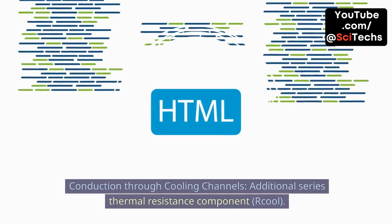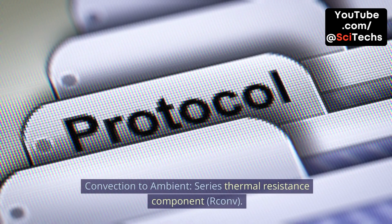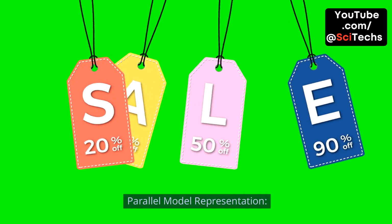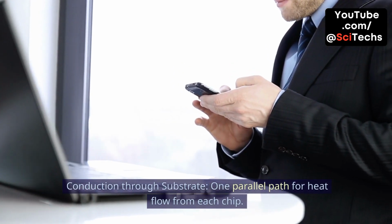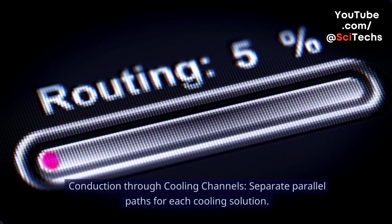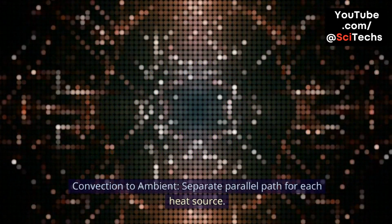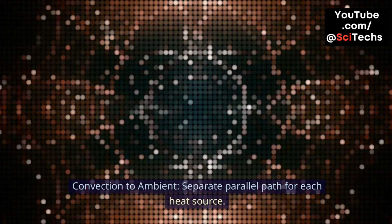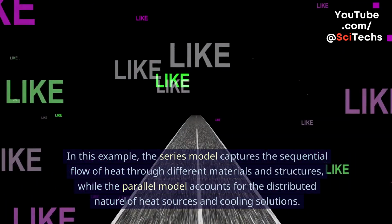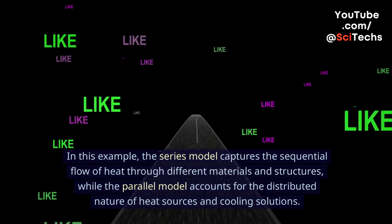Conduction through cooling channels, additional series thermal resistance component, R cool. Convection to ambient, series thermal resistance component, R conv. Parallel model representation. Conduction through substrate, one parallel path for heat flow from each chip. Conduction through cooling channels, separate parallel paths for each cooling solution. Convection to ambient, separate parallel path for each heat source. In this example, the series model captures the sequential flow of heat through different materials and structures, while the parallel model accounts for the distributed nature of heat sources and cooling solutions.